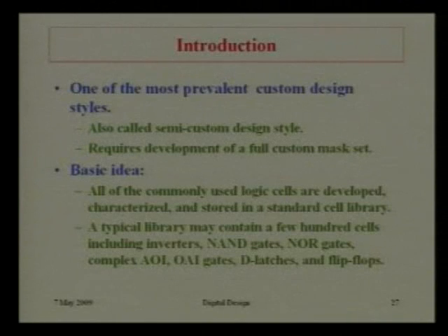Now think that National Semiconductor's fab lab is physically using that 0.13 technology, and that library is given. Earlier we had a 0.18 micron technology library. If we simulate using the CAD tool at 0.18 micron and give it to a 0.13 micron fab, it will not work. Everything is a mess. So that is very important, and everything is given there.